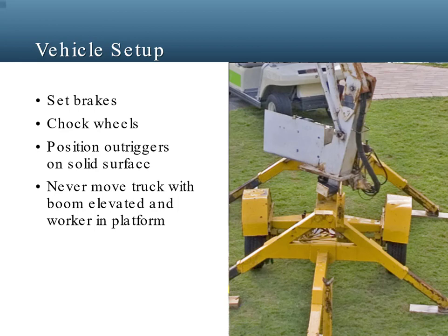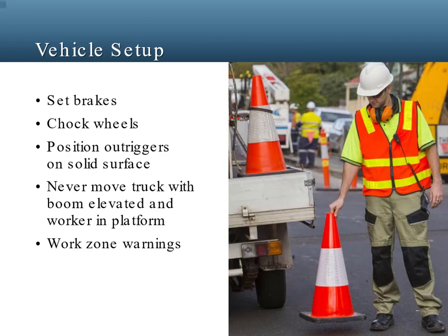Although some equipment is designed to be moved while a worker is in the platform, never move the equipment unless the lift has been lowered and the boom has been retracted. Set up work zone warnings, such as cones and signs, when needed to warn others. Think about the safety precautions you must take when setting up the vehicle before using the aerial lift.